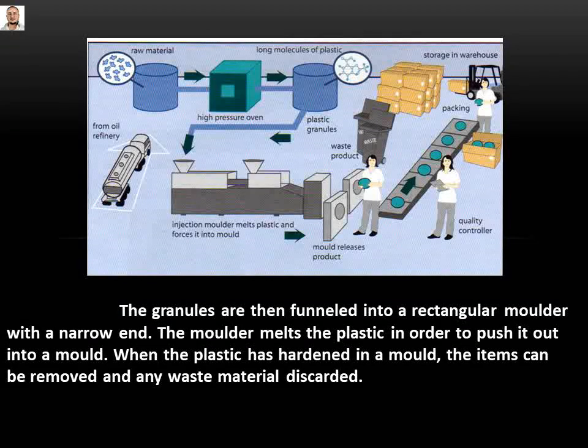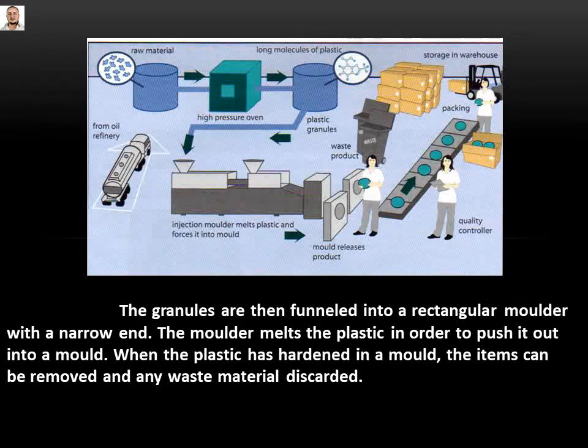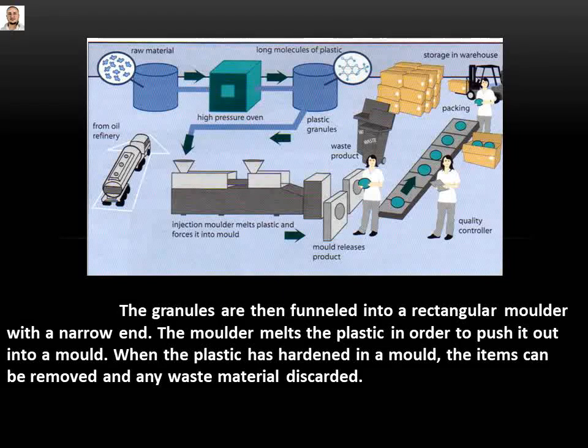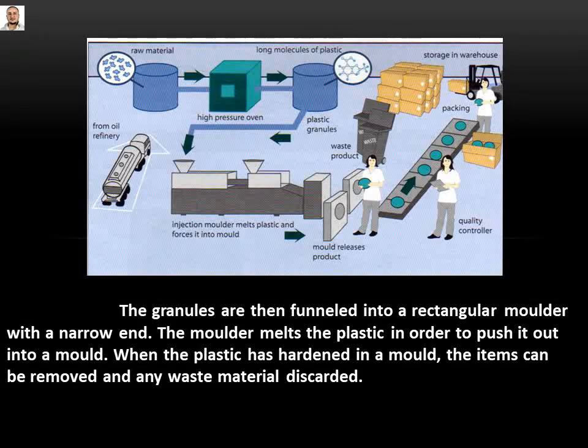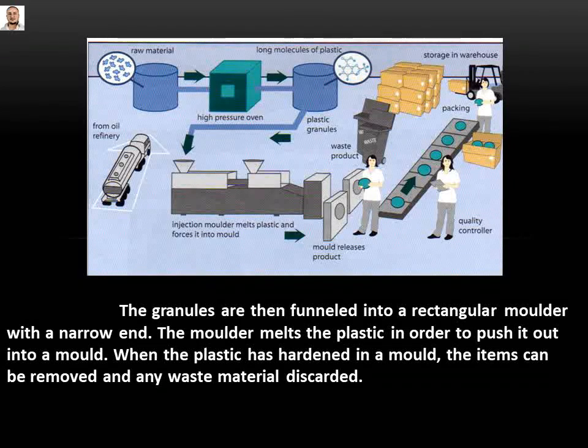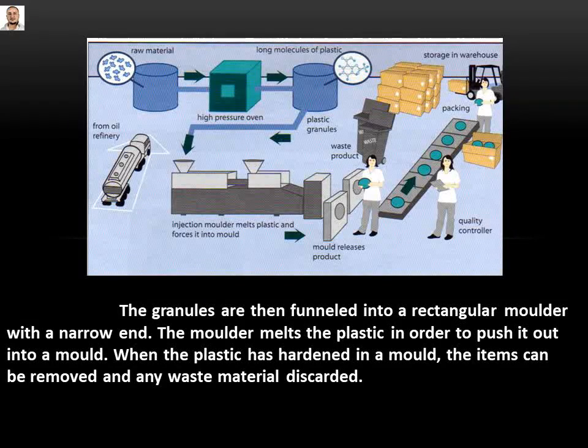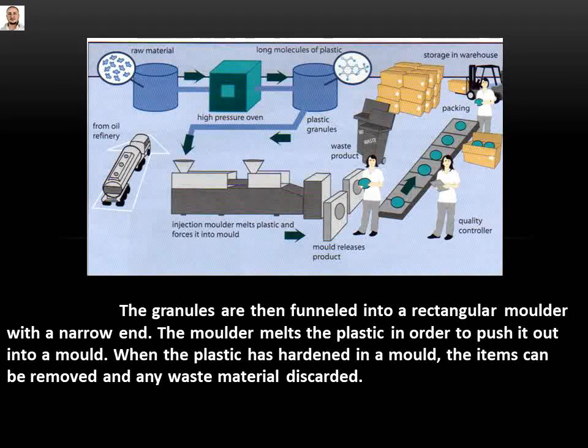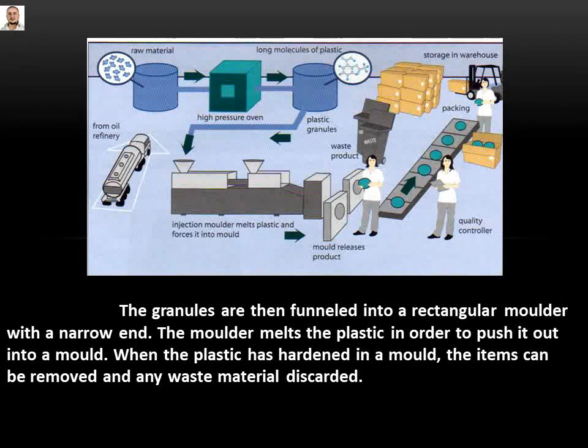Okay, the granules are then funneled into a rectangular molder with a narrow end. The molder melts the plastic in order to push it out into a mold. When the plastic has hardened in the mold, the items can be removed and any waste material discarded.